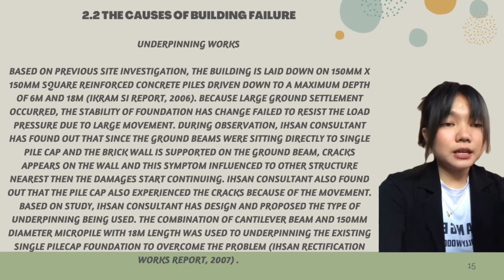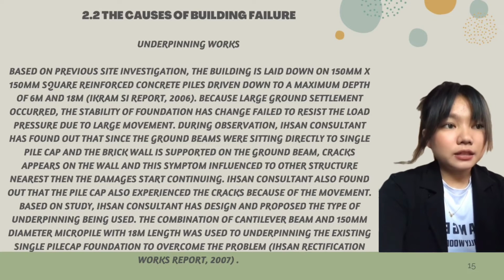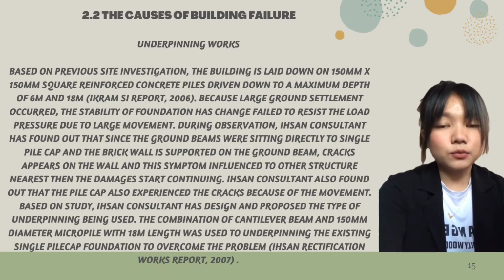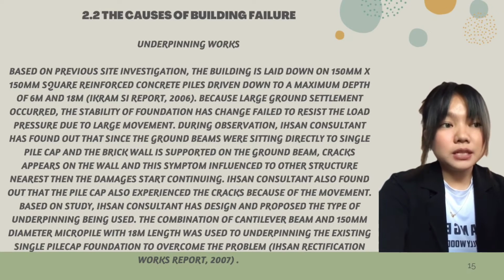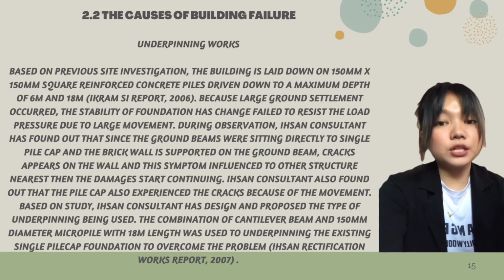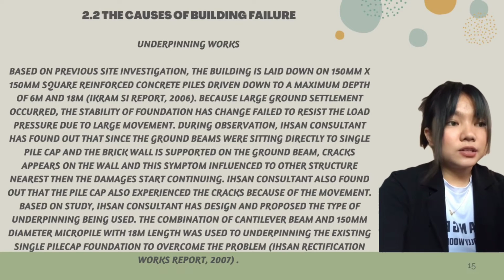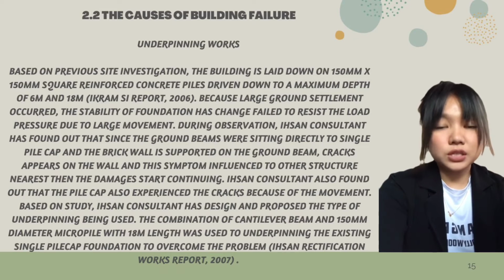Based on the study, a consultant has designed and proposed the type of underpinning to be used. A combination of cantilever beam and 150 mm diameter micropile with 18 m length was used to underpin the existing single pile cap foundations. To overcome the problem, rectification works reports 2007.